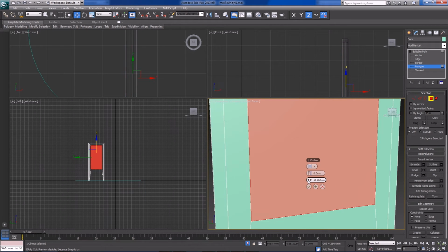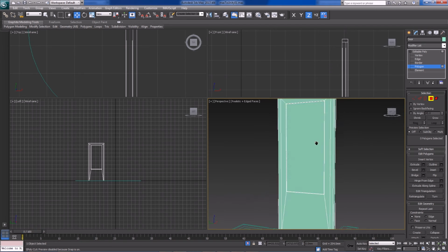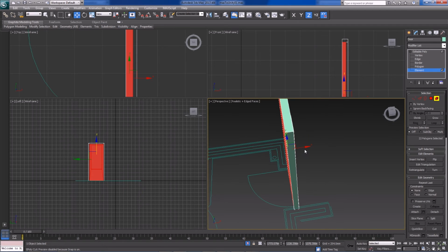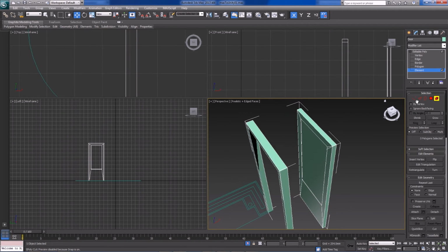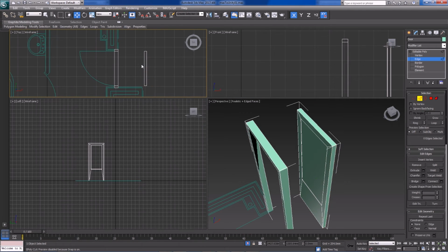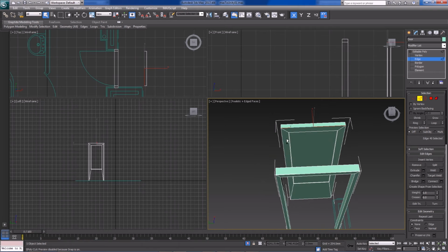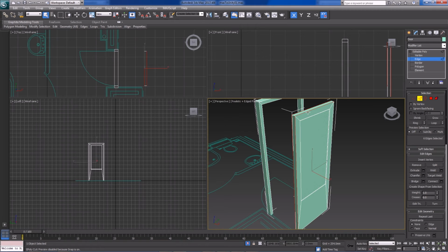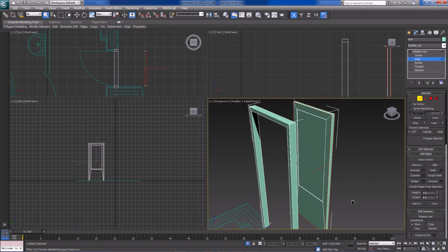That's a bit much. So first let's extrude it. It would be extruded inwards, about -5 millimeters, let's say, and beveled for the same amounts, directly proportionate. And that looks fine. And now you can see that our geometry is correct. So let's just move this out of here for now. Now if we want to chamfer the edges, we can do that a bit more easily. The quickest way to select these edges would be to literally click on them and select them now, because otherwise we'll be selecting everything that is inside the door as well, and then we'll actually spend more time deselecting those.